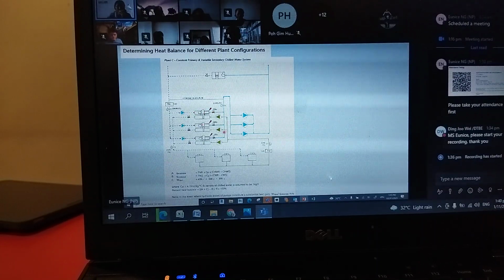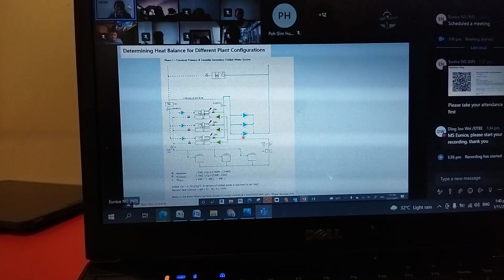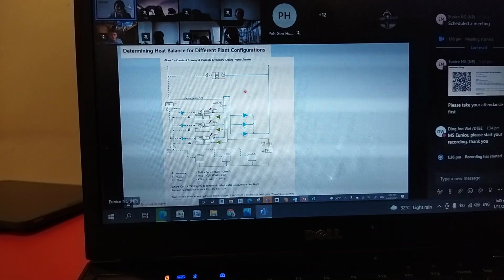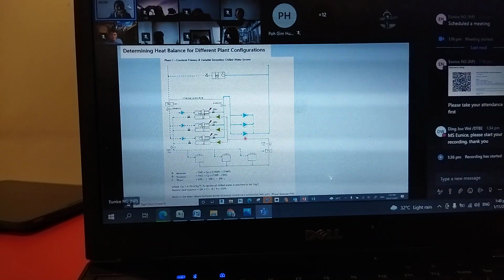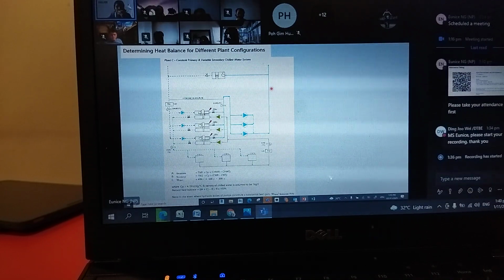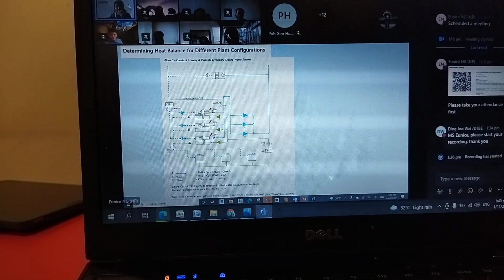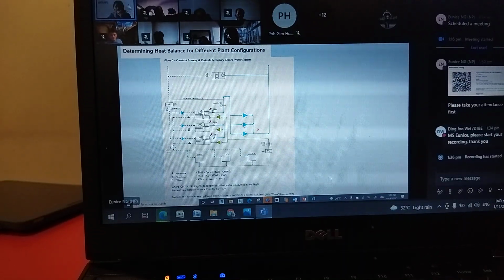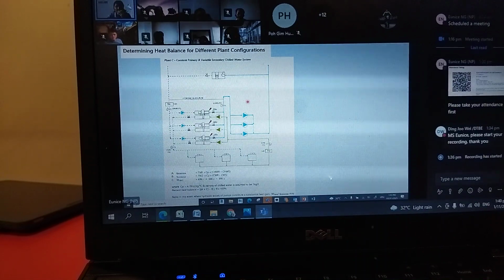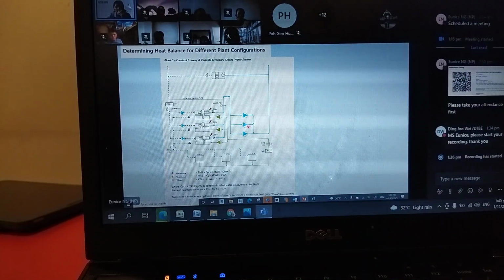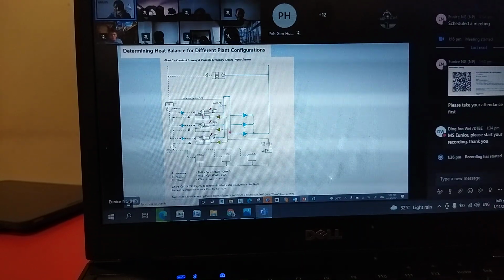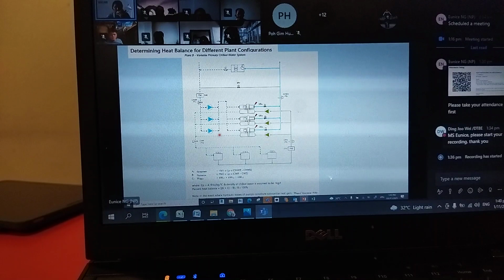And they supply to a common header. Now the chiller always supplies constant flow, but the load is on variable flow. So the secondary pump will be responsible for pumping the water through the secondary load. These pumps are sized based on the resistance of the secondary flow. So this pump will have energy saving, and their size is smaller compared to this case, where there is just one pump and no secondary flow.